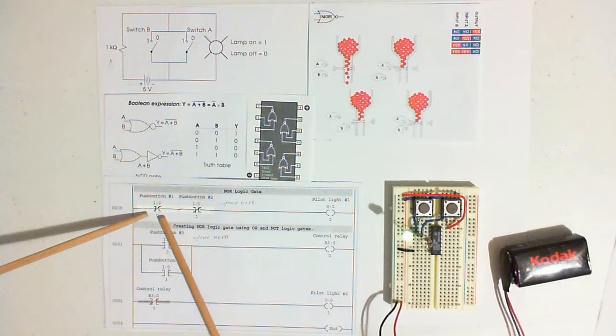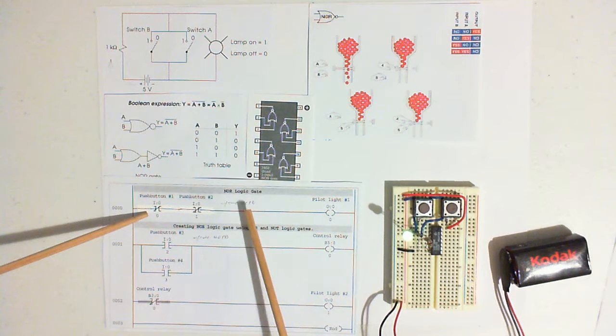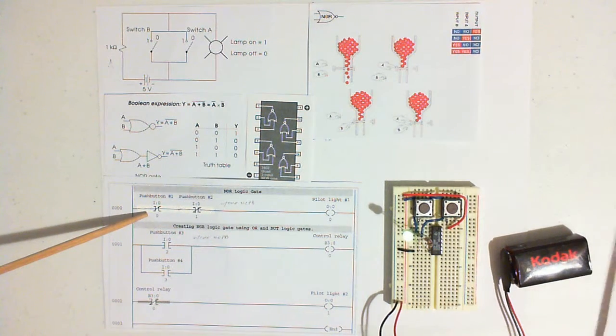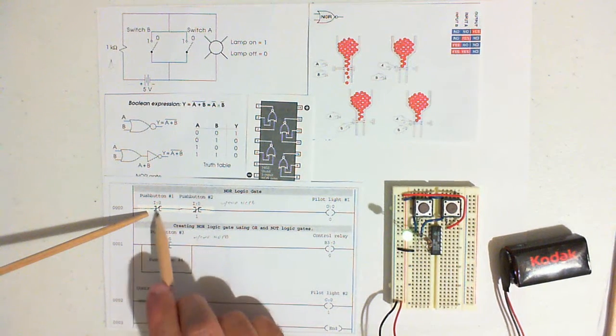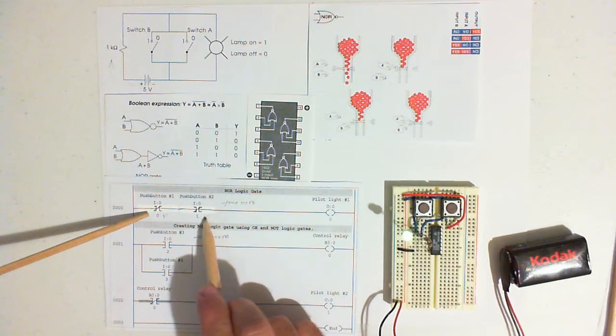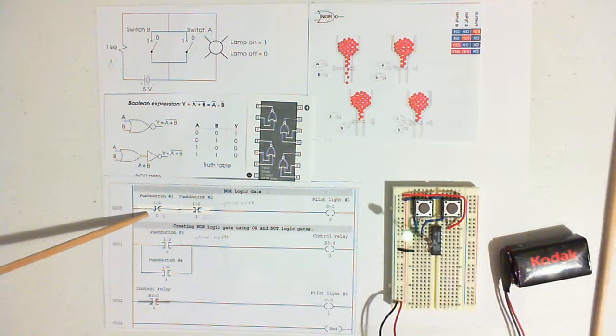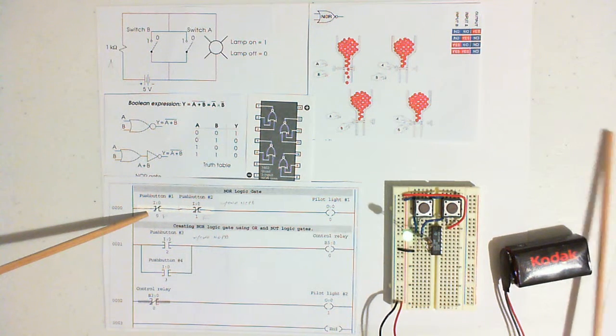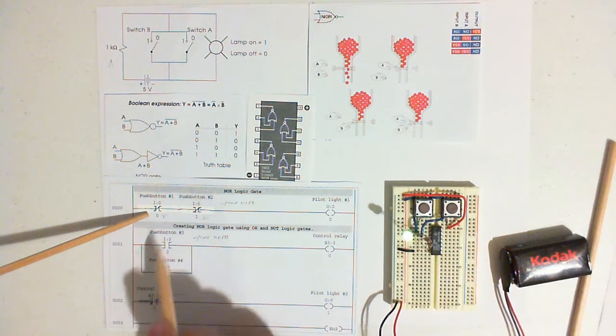In other words, you ask yourself a simple question: is the contact open? No, because we have a normally closed push button addressed to here. Same thing addressed to here. So they're both false. This is a false statement. This is also a false statement. Once you press the addressed push button to here, it opens and becomes true.